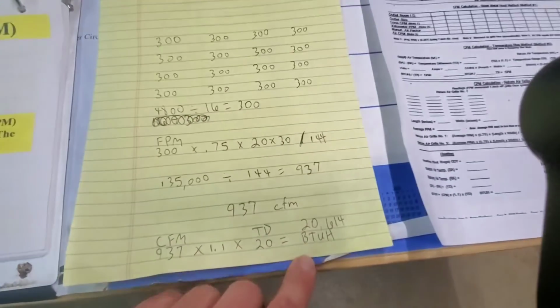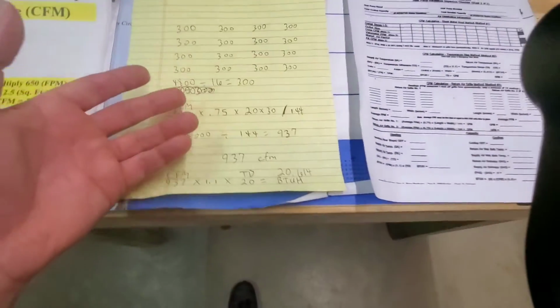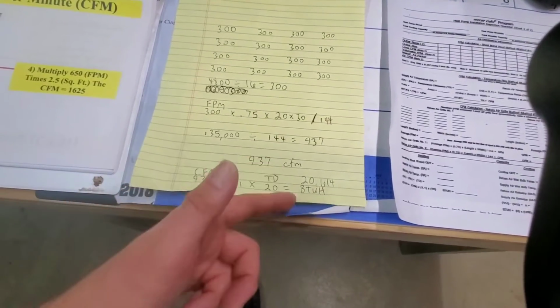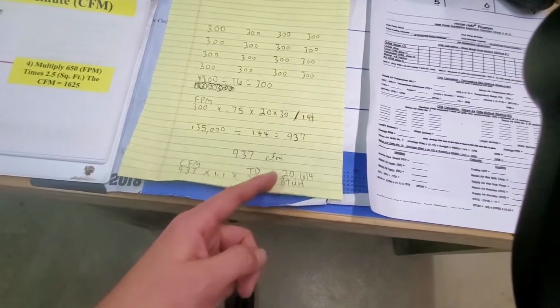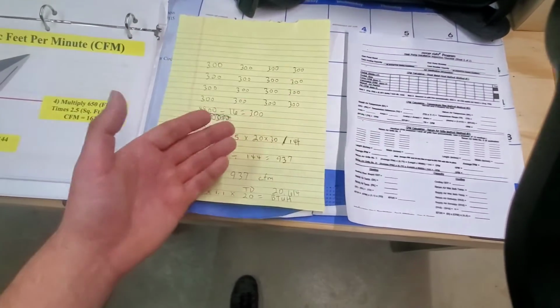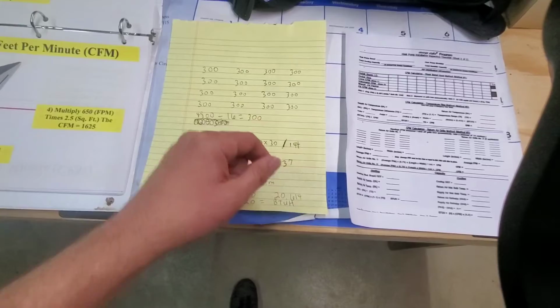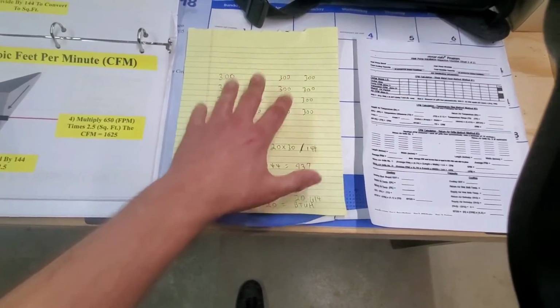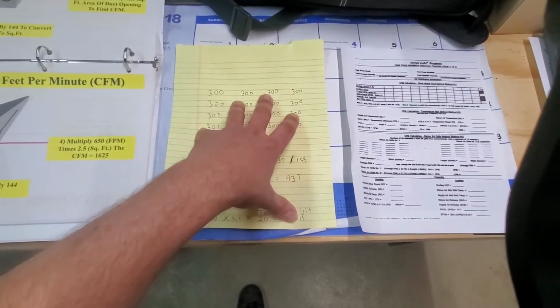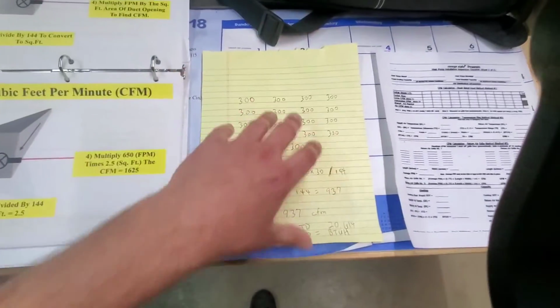If it's rated for 24,000 BTUs, man, I'm almost there. Look at that. I can probably increase airflow to change the BTU. I can decrease airflow to change the BTU, to change the CFM. But this is a great way for me to know, hey, is there something I can do as far as adjusting on the equipment? Or is it the actual ductwork that I need to take into consideration, that there's something that could be wrong?